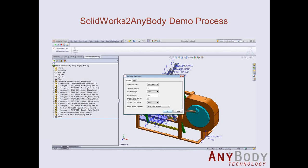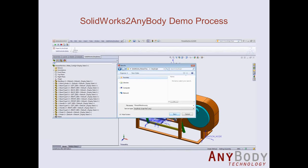About STL files, you can choose which type should be used for encoding STL files, either ASCII or binary format. To translate some Unicode-based object names into AnyScript, SolidWorks2AnyBody supports several encoding methods. After you determine the previous options, you can determine the name and the location of the resultant AnyScript files. SolidWorks2AnyBody will suggest a default file name from the top assembly name like this, but of course you can change it as you want.